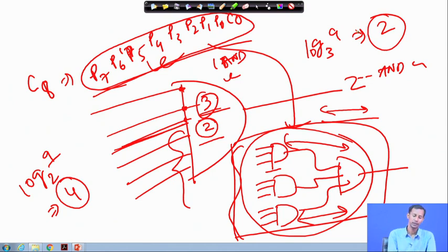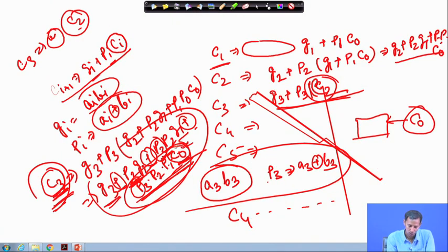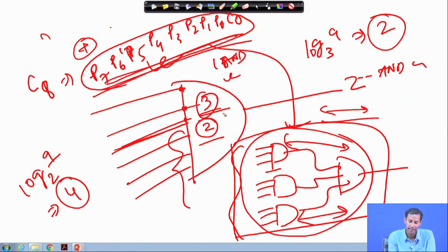So, for these particular terms, there will again be the OR operation. If I go back to this slide, these particular terms will also increase, so this OR operation will also increase. That means I need one OR gate of 8 or 9 inputs for the final ORing operation. Again, with the fan in limitation of 2 or 3, the level will increase something like this.